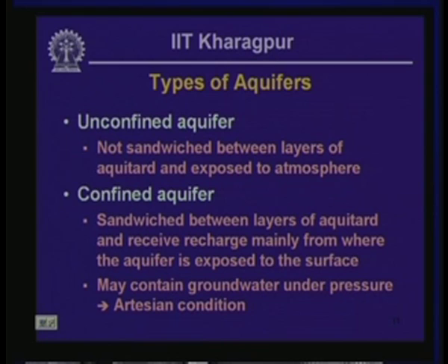An unconfined aquifer is not sandwiched in between layers of aquitard, and the aquifer is exposed to the atmosphere at some recharge point, because if the aquifer is not exposed to the atmosphere, at least locally, then it is not going to be recharged by infiltrating groundwater, and it is not going to be classified as an aquifer at all.